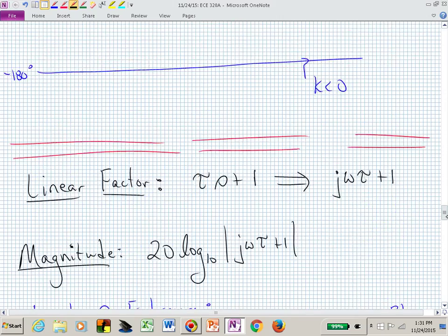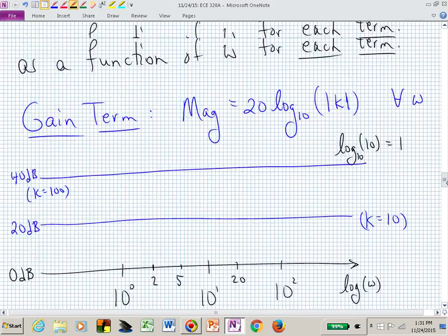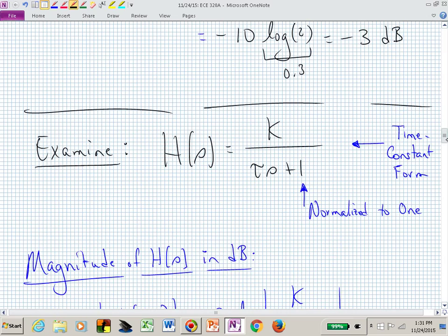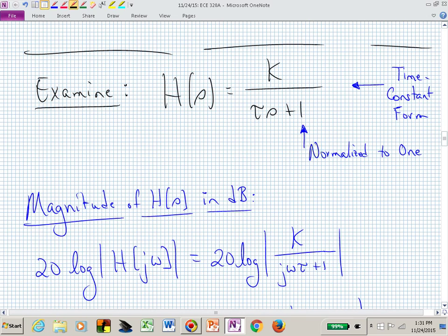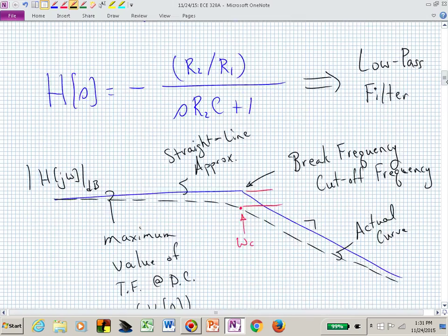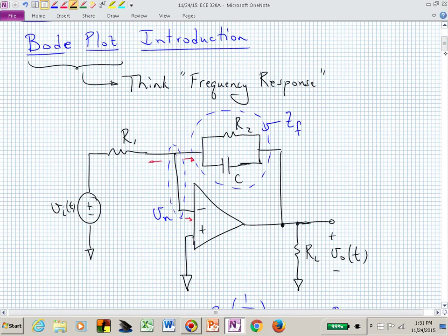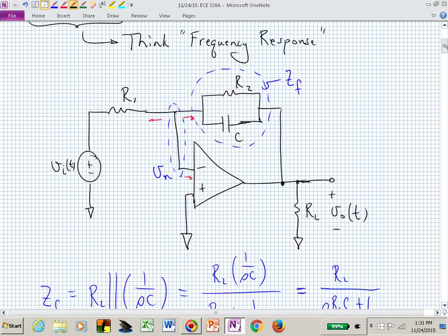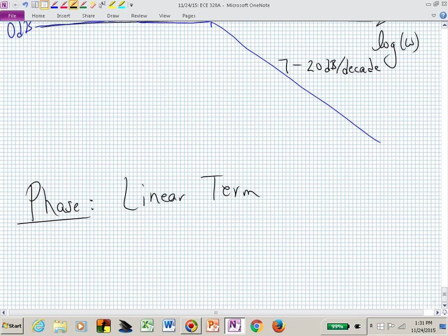If somebody gave you that, you could now build that with this. So you now know how to build a first-order low-pass filter. We will then find a second-order filter, and now you can break everything up into second-order pieces and first-order pieces. A fifth-order filter is now two second orders and a first order, and you put those together. So we will learn how to do that after the break. Is that okay?